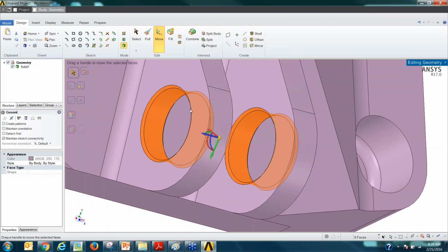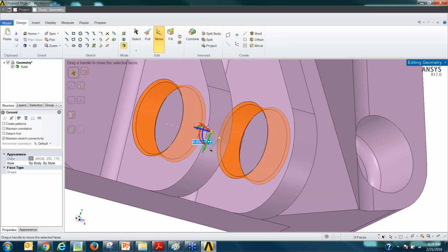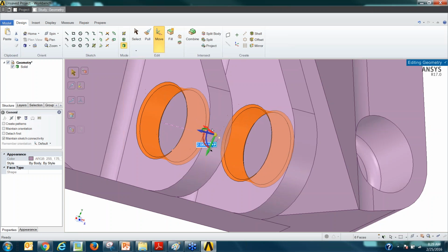So let's say I want to move. I'm able to essentially move, and as I move you see some dimensions coming up there, right? And I do see a little tag. Now, this is very important, because I can use this dimension as a parameter wherein I can make a change in Ansys AIM. I'm able to use it to run optimization studies, or I should say design exploration studies, wherein you can use this dimension and create a table with different checkpoints for different values and then see the output of deflection or stress, right?